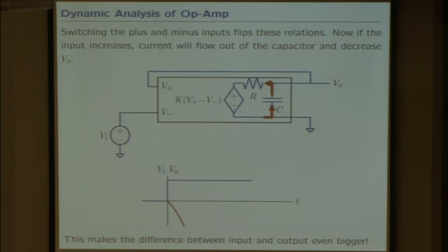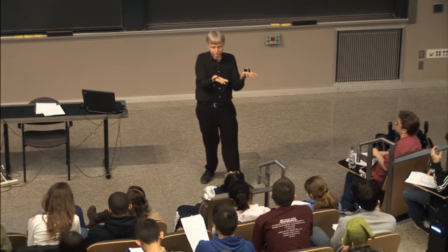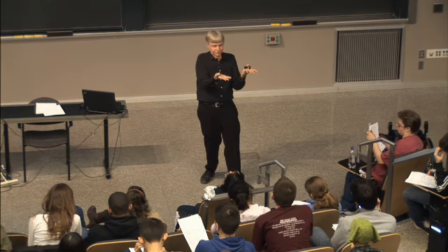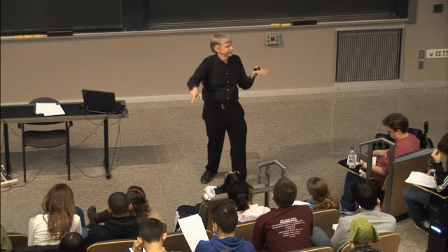If I put the input into the minus port and the input goes through a step, then the input going positive makes the voltage-controlled voltage source generate a big negative voltage. It sucks current out. So the input went positive, and the output goes negative.